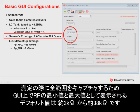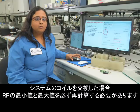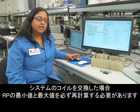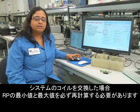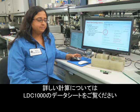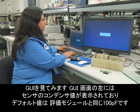In order to make sure that when doing any sort of measurement that we capture the entire range, the default values that you will see on this GUI for RP min and RP max are around 2 kiloohms to about 38 kiloohms. When you change out the coil in your system, you need to make sure that you calculate RP min and RP max accordingly. The detailed calculations can be found in the LDC1000 datasheet. As we move into the GUI,